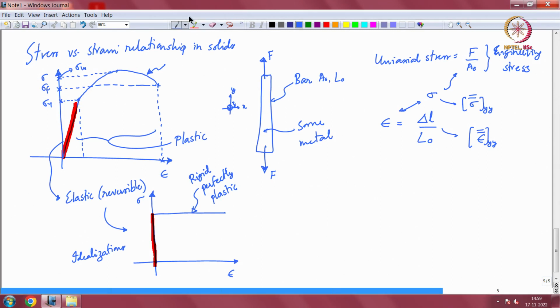That is one end of the spectrum, when the material can deform quite a bit. So, it is very ductile, you can use the rigid perfectly plastic assumption. At the other end of the spectrum you have a material that does not deform plastically enough, and that basically goes like this, and breaks, okay.